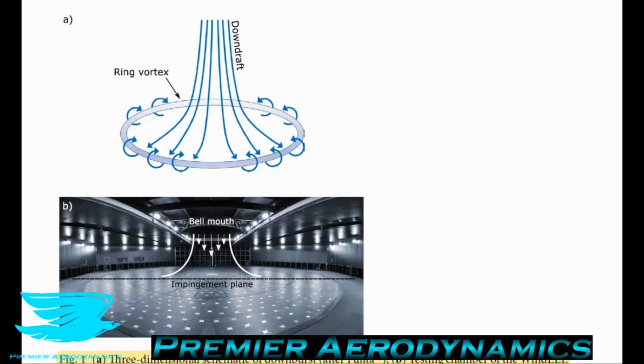nevertheless, the facilities that are capable of creating downburst-like impinging jets are still few and sometimes limited by small scale or, for instance, continuous impingement of the jet that creates a 3D but steady state outflow near the surface. So this is still one problem because you have to have such a big wind tunnel to produce similar timescales.